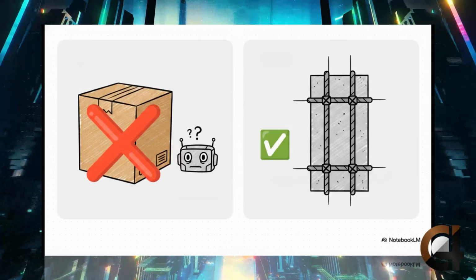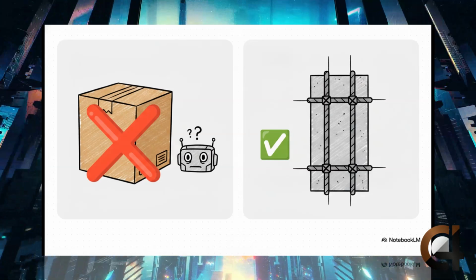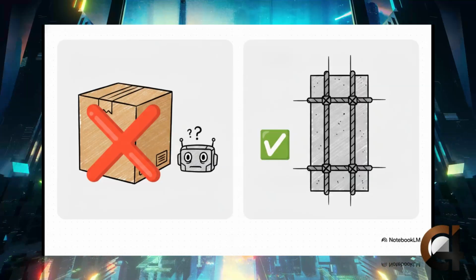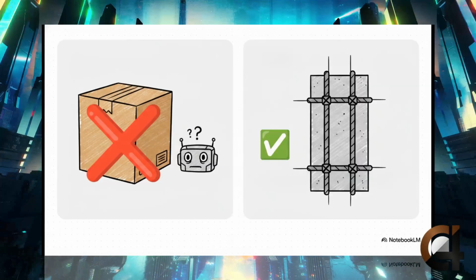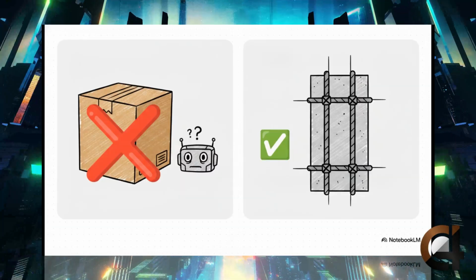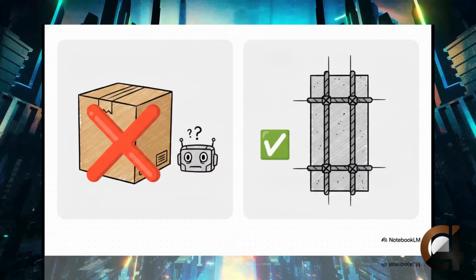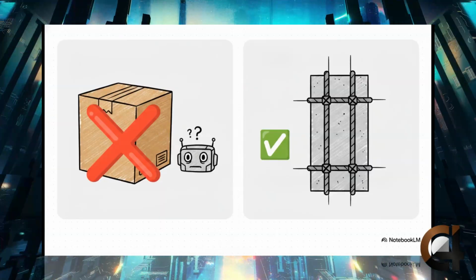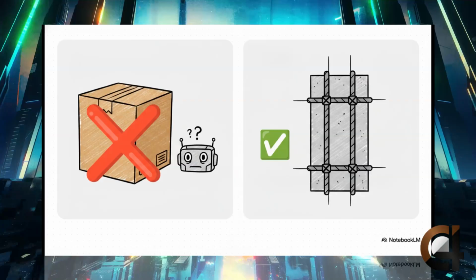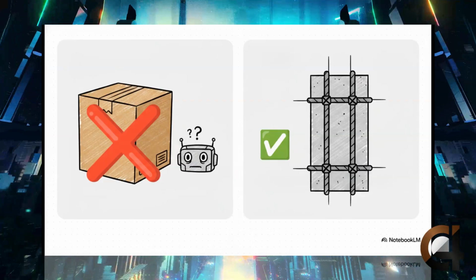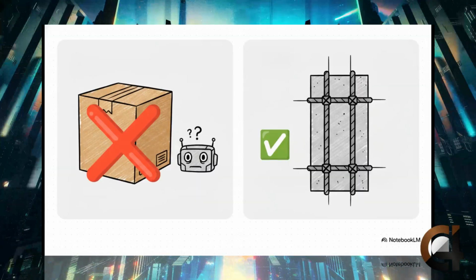Down in the bottom left, under the column reinforcement details, it describes the outer steel loops holding the main bars together. But read the label. It says 9mm at storage at 225mm center to center. Wait, storage? No way! The correct structural engineering term for these loops is stirrups or links. Seeing the word storage right there is a glaring hint that an automated tool, perhaps an AI, might have misinterpreted or hallucinated text during the drafting process.